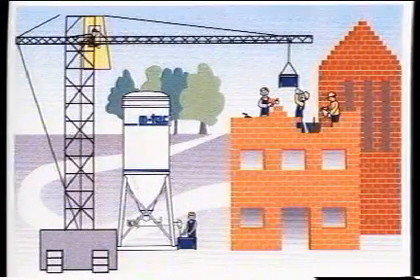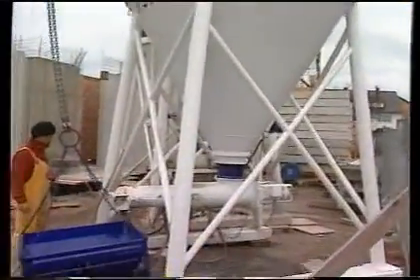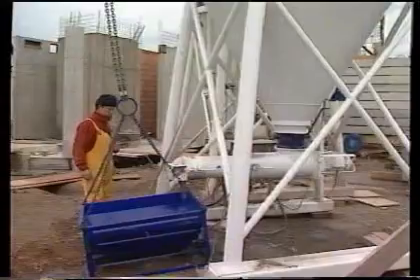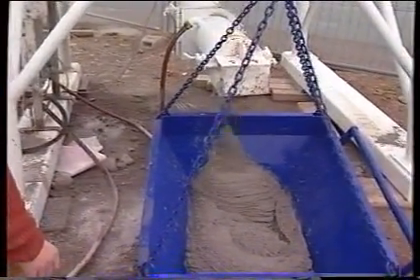The m-tec silo mixing station is another variant of masonry mortar application, allowing fresh mortar to be conveyed at the push of a button from the continuous mixer into the crane skip.